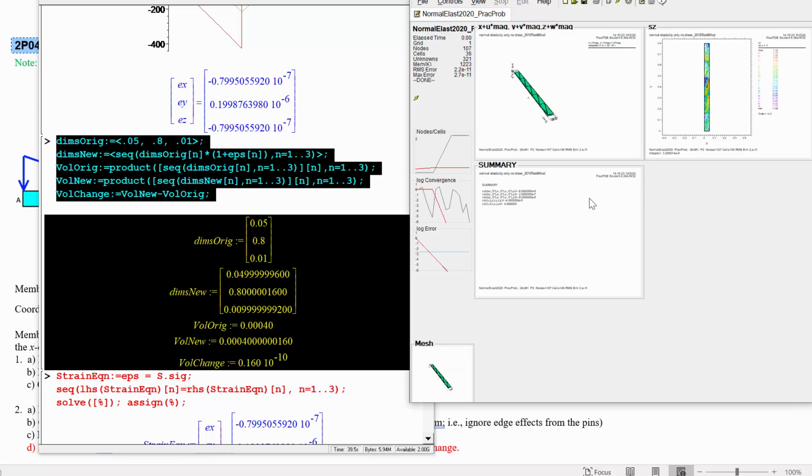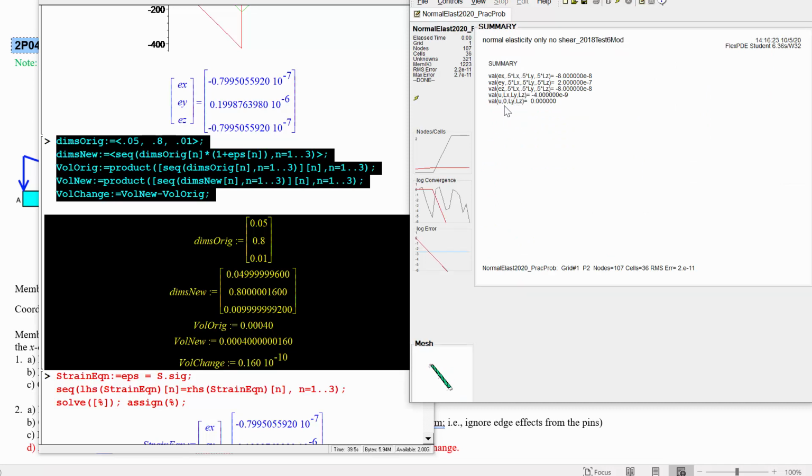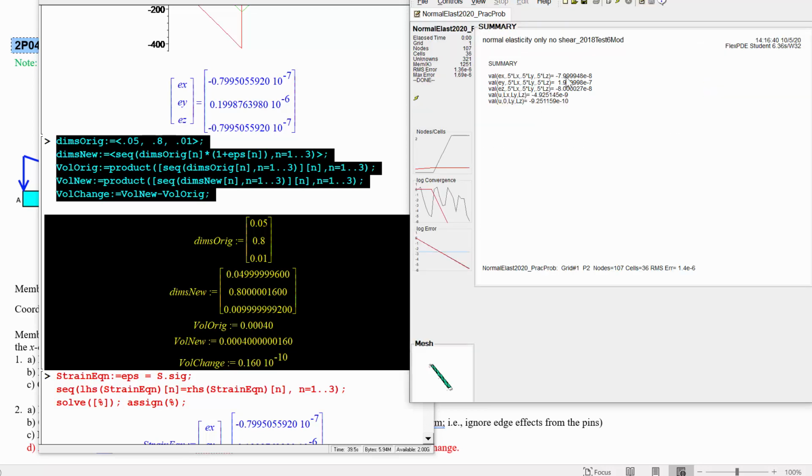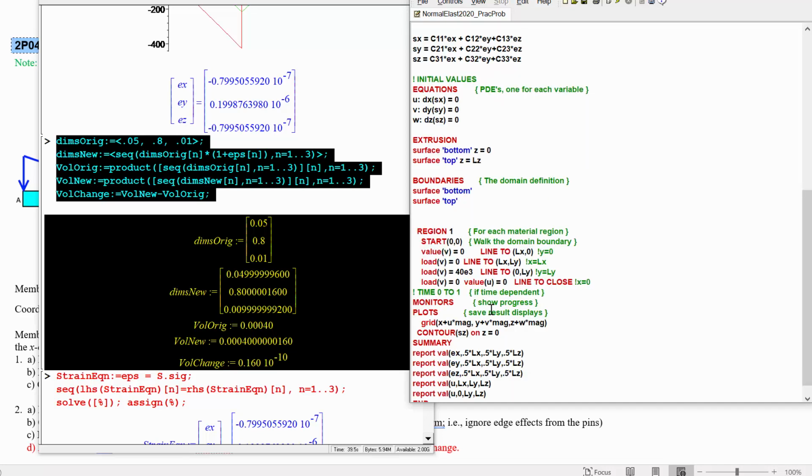And now we've got it nice and fixed so that this whole surface doesn't move. Notice we didn't actually change the other values. I think actually we made them closer to what we would have thought. There's actually less round-off error by helping the program out and saying, you know what, x is not allowed to move in the x direction.